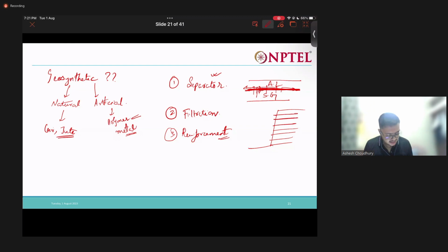There are layers of geotextile or geogrid that are placed. First there is one layer of soil, then one layer of geosynthetic material, then one layer of soil, one layer of geosynthetic material. Like this, reinforced earth structures are constructed, and this geosynthetic material is tied into the fascia walls.